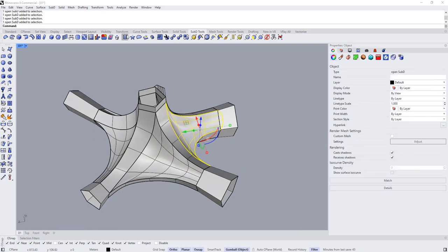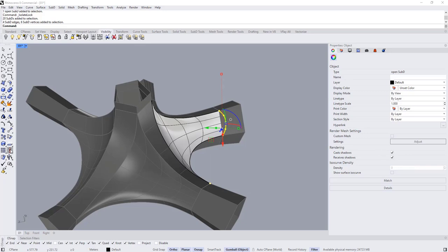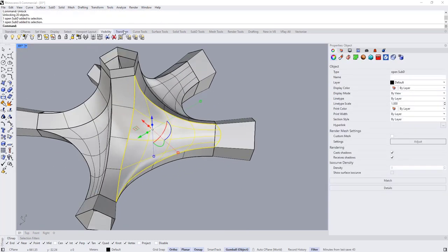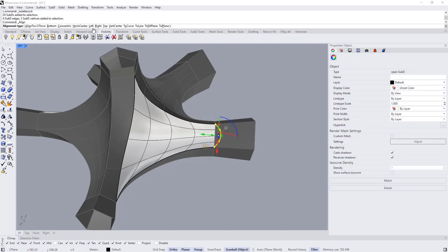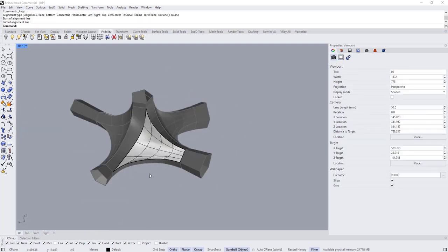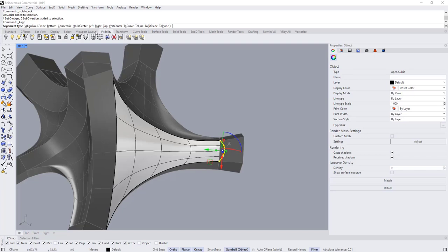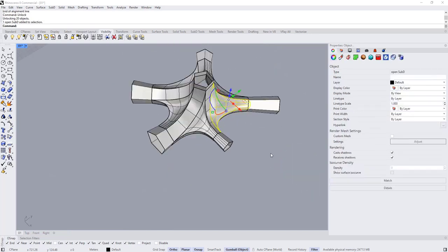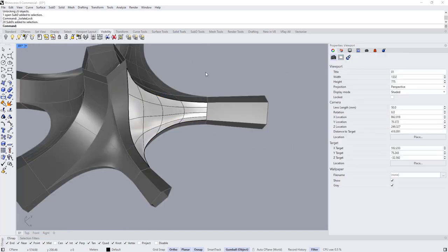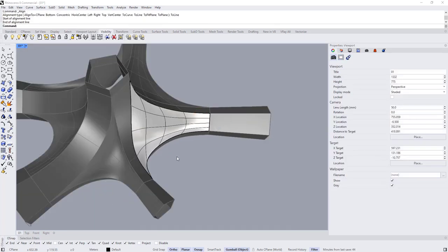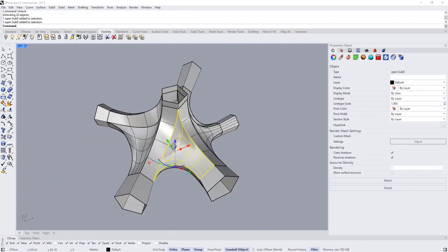Now I'm going to repeat this align process for all these faces. So select this one, go to visibility, isolate, hold Control Shift, select all these points, choose align, choose to line, and let's align it like this. Unlock, select the next one, visibility, isolate, align to line, and draw a line here. Repeat the same for the remaining faces. Unlock. Okay, now all of them are adjusted.